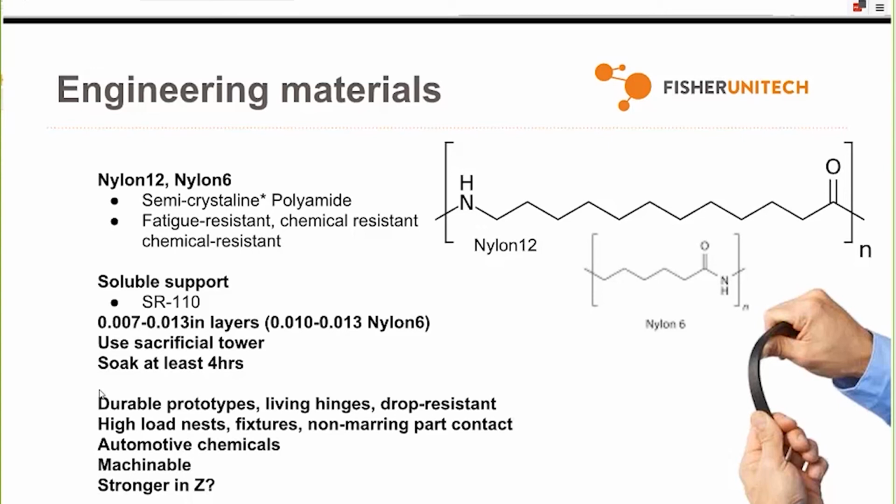Now, the last thing I want to mention is, well, I have personally found nylon 12 to be especially strong in the Z-axis. It doesn't seem to break along the layer lines like most other materials do. Now, if you're looking at the spec sheet right now, you will notice that that spec sheet doesn't really corroborate that claim. And I haven't really done any rigorous tests to confirm it, but I still think it's worth mentioning.